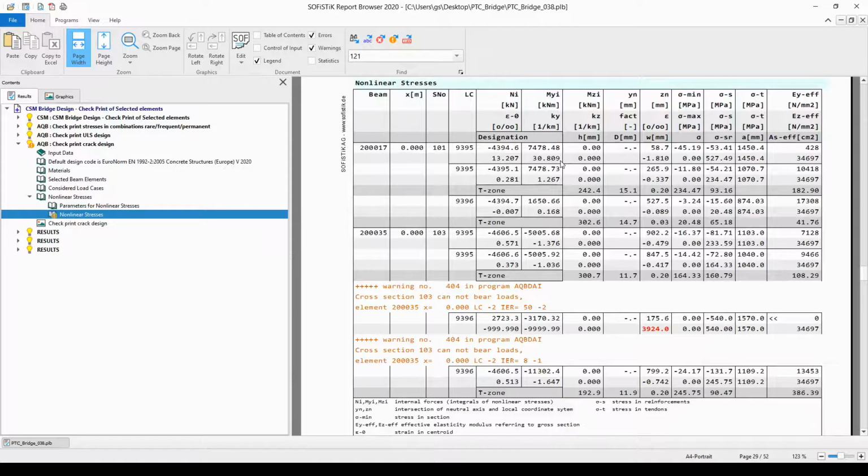However, as you can see, there is no third line standing for the H, the D and the crack width itself. The reason is that first, the software tries to fulfill the crack width criteria with the amount of the minimum reinforcement in the cross-section. If it is satisfactory, then the crack width is presented at the third line at W.